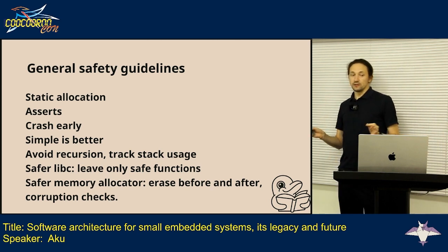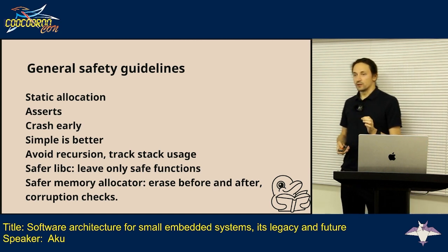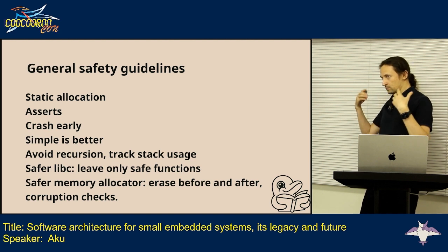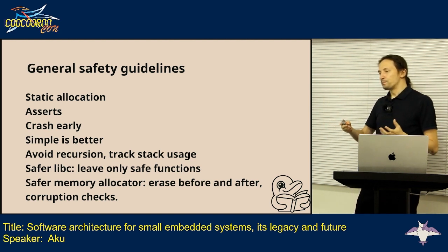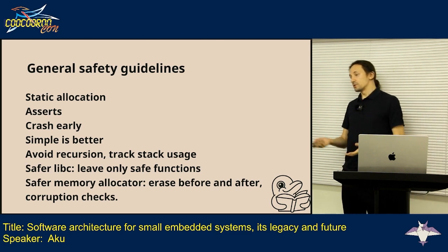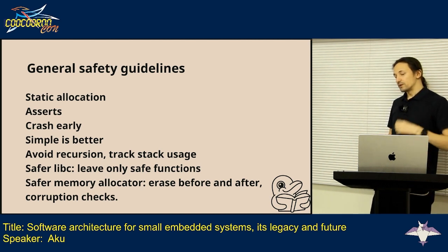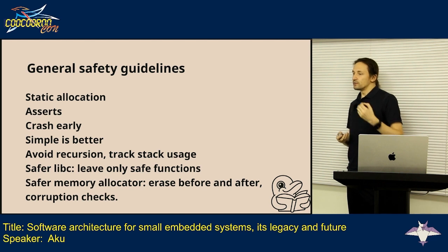And that will be totally fine. But on an embedded system, let's say we reached the point where heap fragmentation means we can't allocate the next block. So what should we do now? The only option for you is to crash. And the earlier you do that, the better for you, because it's easier to spot those issues in development and fix them.